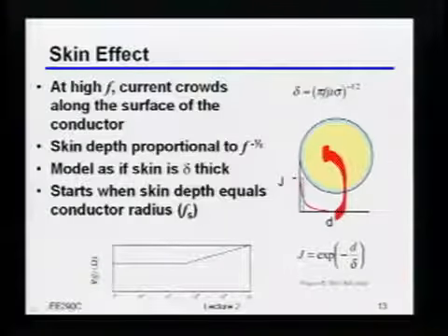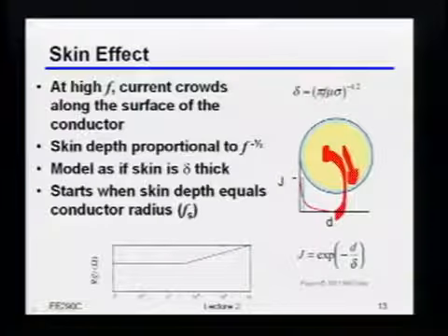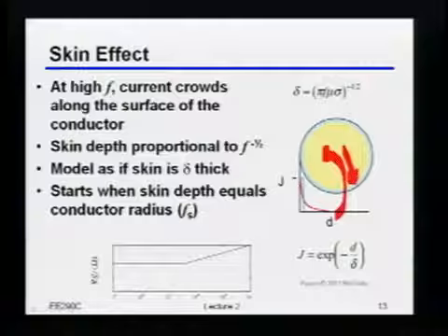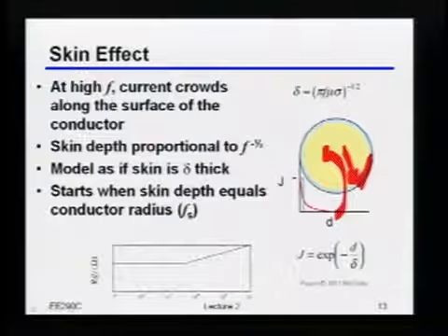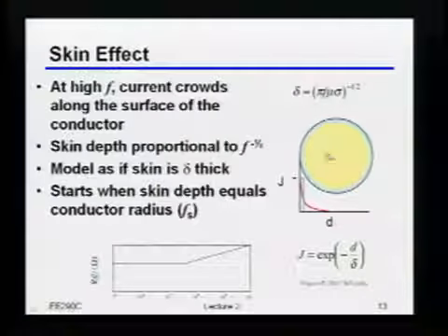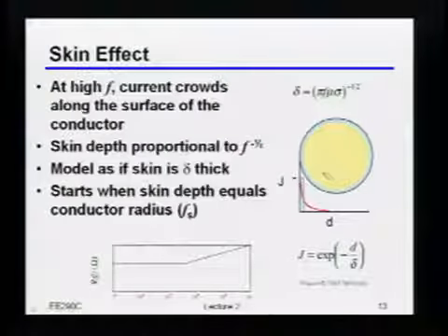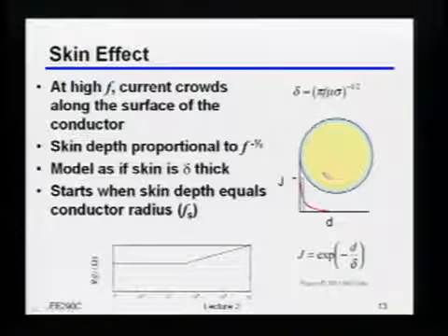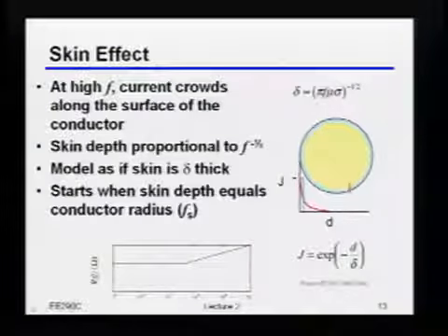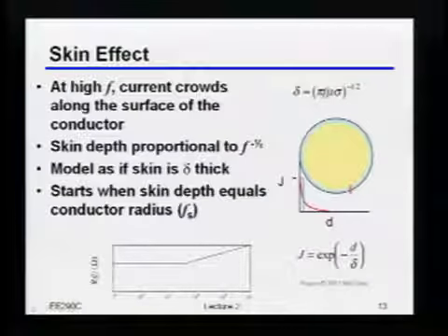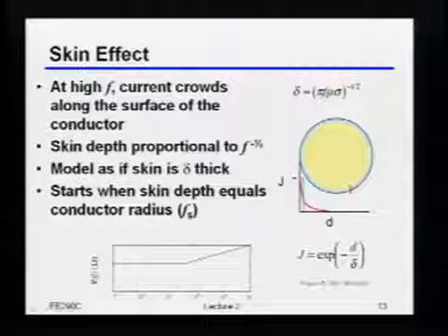Because if I actually had current in the middle, I'd have to traverse through the wire, and that would cause me some inductance. Whereas if I'm always flowing on the edge, then that just reduces the inductance that I have, okay? So you'd think that maybe that's good news, but turns out that's actually bad news because it means your loss is going to be higher, right? Because the effective thickness of the conductor is not really set by physically how thick the thing is, but actually by how high of a frequency you're signaling at, okay?